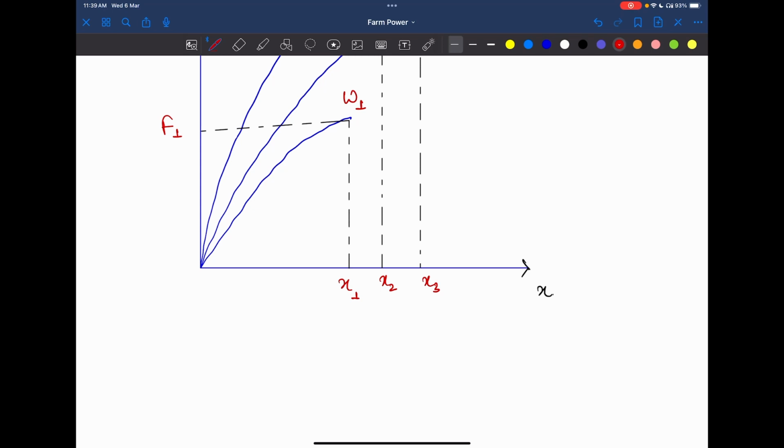We find that for a soil having some cohesion, the force F doesn't approach 0 as W approaches 0. If the maximum values are plotted for a soil that has both cohesion C and internal friction phi, the result will be similar to this.